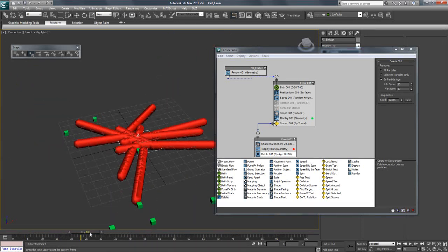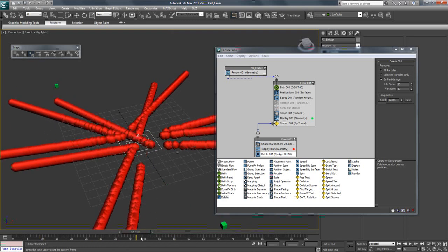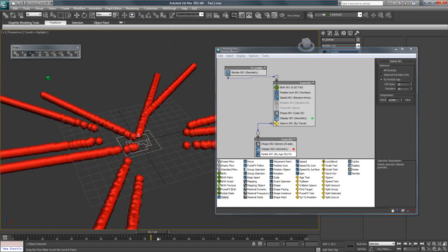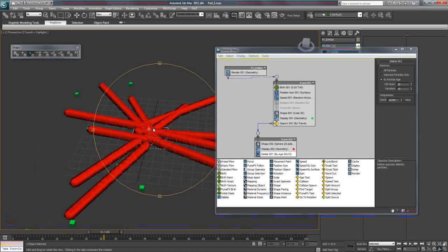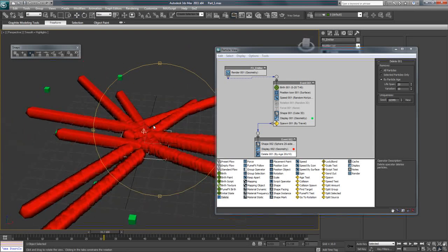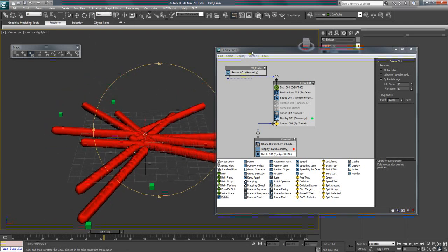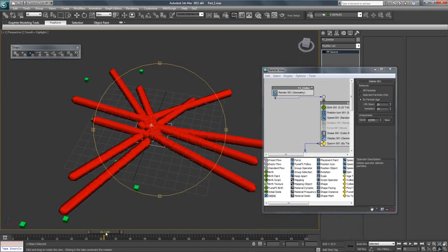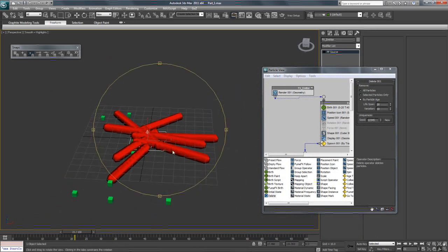We want these particles to just keep moving from left to right, and not have these particles just stay on. We're just going to try out certain ways to get the particles to die off. So if you add delete and you go to particle age, change it into lifespan, we'll have them delete. Obviously, the shorter it is, the sooner the particles are going to delete. The longer it is, the longer they stay on. So later on, we may tweak that depending on how the animation works out. But you can see, if you play back, exactly how everything's working so far.